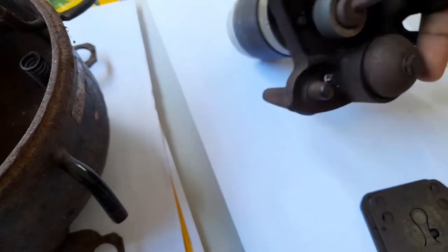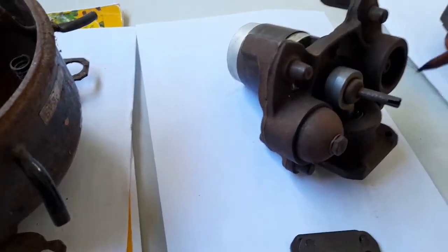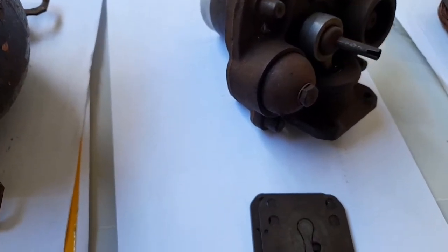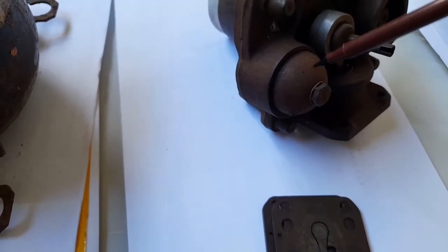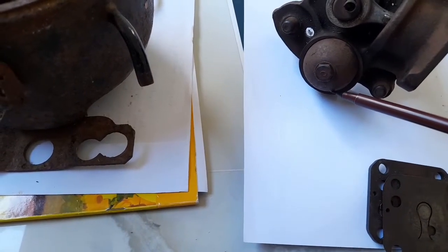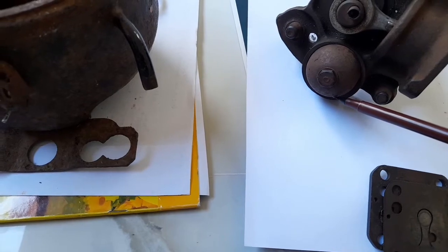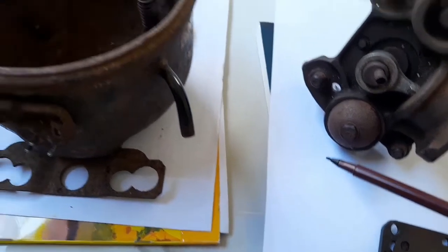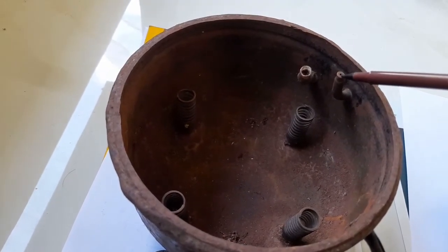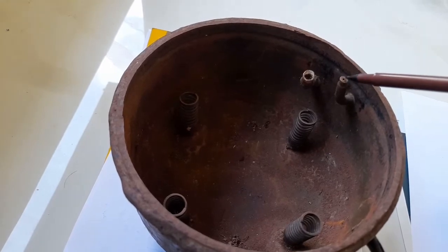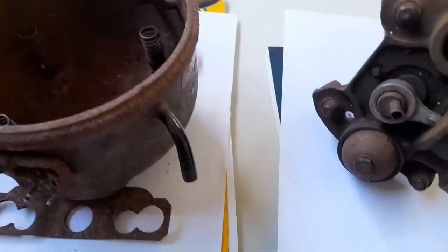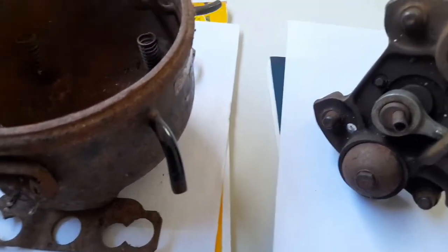The compressed refrigerant is sent into this muffler provided at the exit side of the compressor, and then there's an opening here to which the delivery line is connected, and finally the delivery line is connected to this small tube, and through this small tube the high pressure, high temperature refrigerant is delivered to the condenser. So this is how the entire compressor functions.